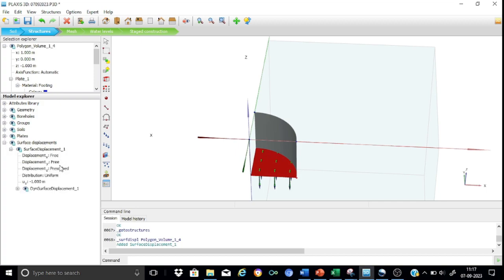The x and the y direction will assume the free boundary condition, and it has set the prescribed condition. And here I would like to use minus 0. We'll take this footing to an elastoplastic condition by subjecting it to a prescribed displacement of say 400 mm, that is minus 0.4 meters. So that's good enough. So let me just save this model again. So this means we are now ready to move on to the staged construction.